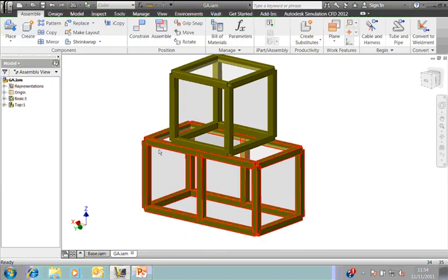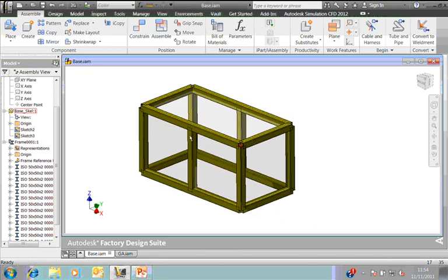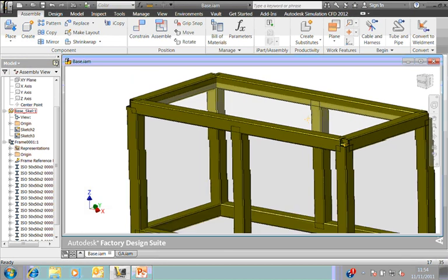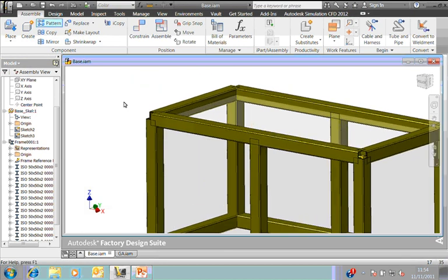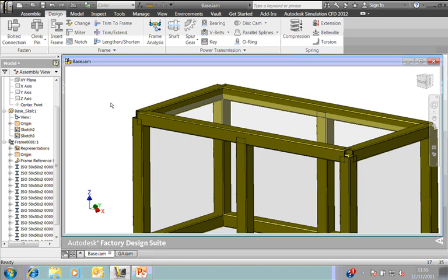If I take this bottom assembly here, we would probably want to start to work on this analysis, or on this frame. Now we finished the analysis. A lot of companies probably would want to just run and create a quick and dirty frame generator model first, do the analysis, and then afterwards start to trim and extend and miter to create the final design.